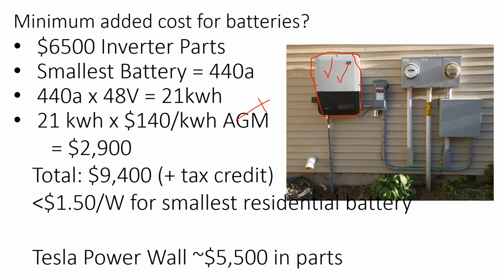And in the meantime, what SMA has right here is a power outlet that gets stuck to the side of the inverter. It's a separately derived power outlet where you can get up to 2 kilowatts of power out of it when the grid is down. So even without batteries, the SMA inverter is able to produce some power through that controlled outlet. And this doesn't have to be an outlet on the side of the inverter.